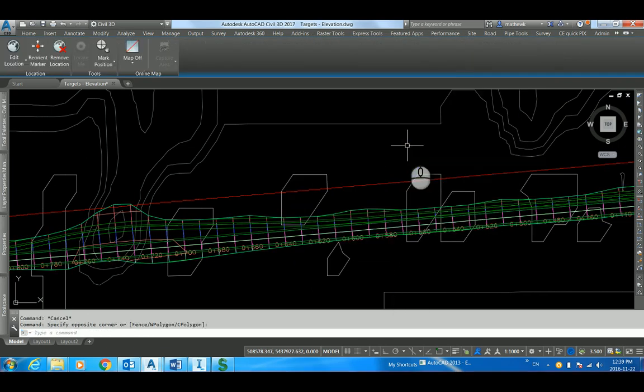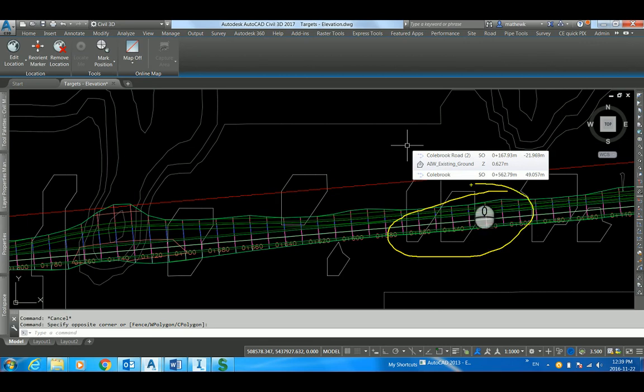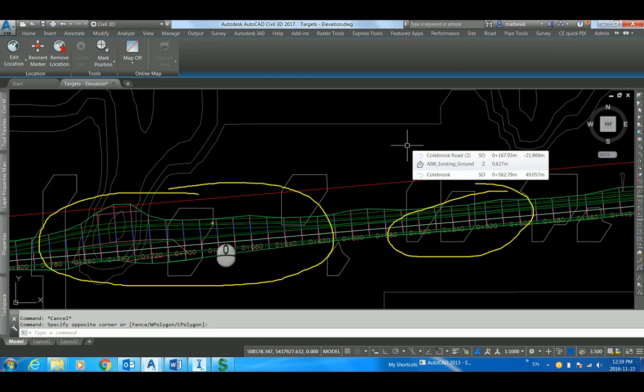Once the corridor rebuilds itself, the ditch behaves as intended. For example, in this section, the ditch is still 750 millimeters below the hinge. In this section, you can see the foreslope getting wider. It maintains 3:1 slope, but as it gets wider, of course, the ditch gets deeper.